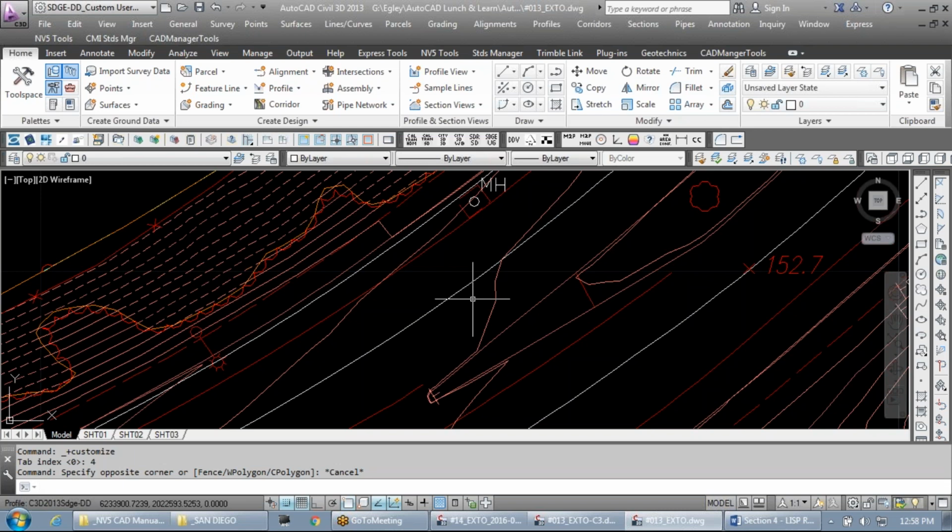And that's my major gripe with annotative text, is that it's dependent on where you want that insertion point to be. And that insertion point is different for every single annotation scale, right? So have you ever seen that where you have annotative text and you have like 4 different locations of that text? It becomes very hard to use, and that's my main gripe against annotative text. So just be aware of annotative text. Make sure you're using it appropriately, that you mean to use it. Don't be creating annotative text just because it's there. Typically text that I create, it's not annotative. So when it says annotative, typically we'll say no. But there are times where you will want to use annotative text.